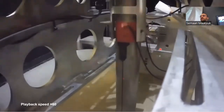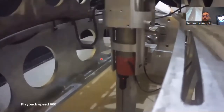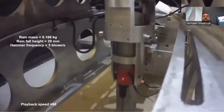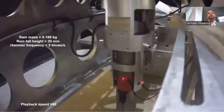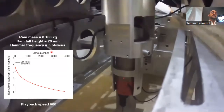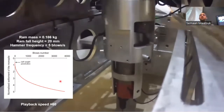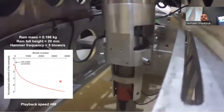Then once I reach 100G, I start to install the monopile by impact driving using the hammer, keeping the same hammering characteristics. And as observed, the monopile driving became less and less fast, and so the number of blows increased with the penetration depth, as shown here in this figure, representing the number of blows as a function of the normalized settlement of the monopile. And once the monopile reached the desired depth, I stopped driving it.